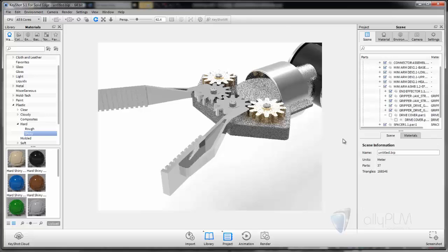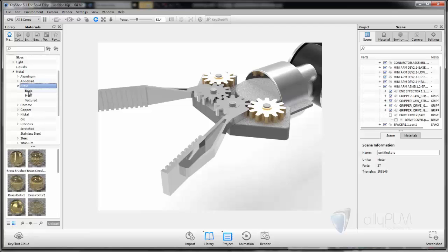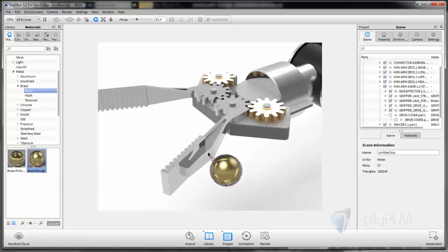You also see in KeyShot that we have, similar to Pathfinder in Solid Edge, a scene tree, and we're actually able to hide different components of this part, identical to what we do in Pathfinder in Solid Edge. Now we'll add just a few more materials onto this part.